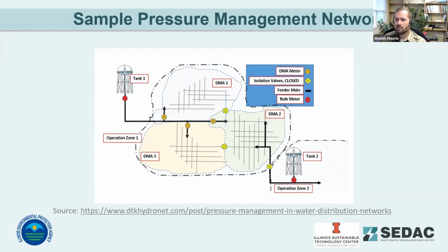And you're trying to maintain the minimum pressure that you need to satisfy your requirements. So you're minimizing how much pumping you have to do back at the plant. That's going to give you your big energy savings. It's going to minimize how much leakage is coming out of existing leaks in the system. By not having large pressure swings and rapid changes in pressure, you're not going to create new leaks by pipe vibration, expansion, contraction, things like that, that exacerbate leakage over time in a distribution network. And that's where big savings come from for these.